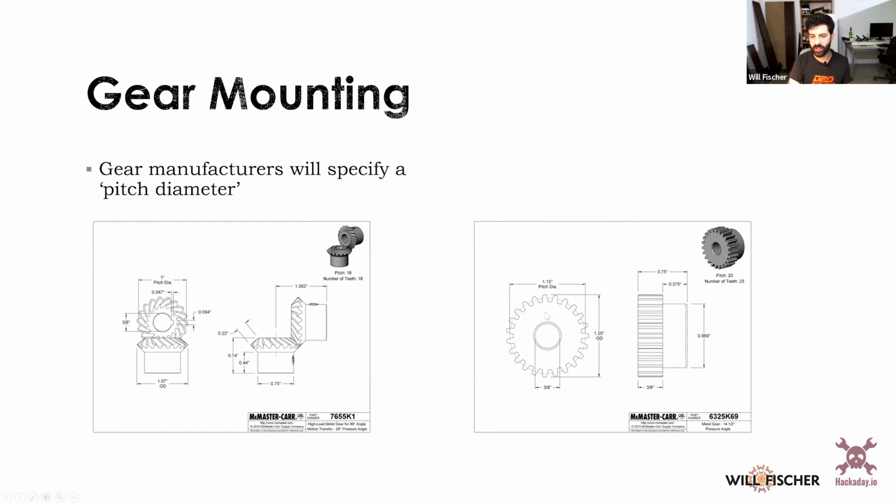So over here in the spur gears, you'll notice that it gives you a pitch diameter. This is an American part, so it's in inches. And then if I'm meshing that with one of the same, then I know that that's my mounting distance axis to axis. And if I'm doing a different sized gear, then I have that number and add it to half this number, and that gives my mounting distance between the two. That's how you do simple spur gears.